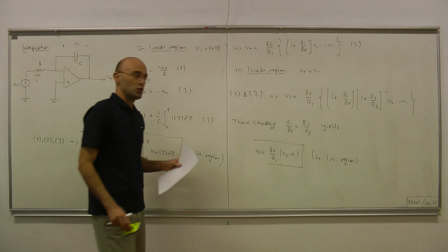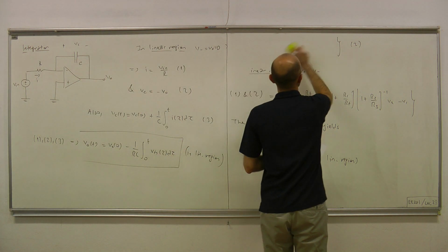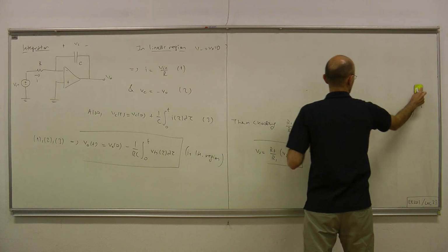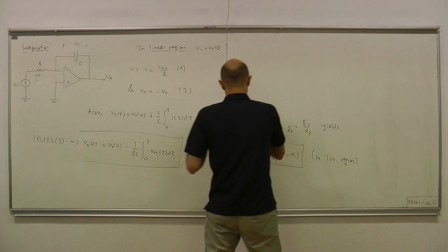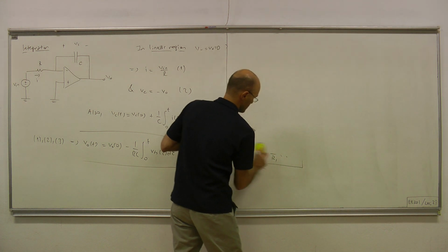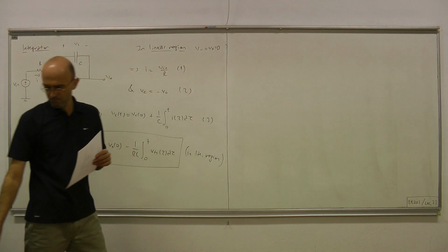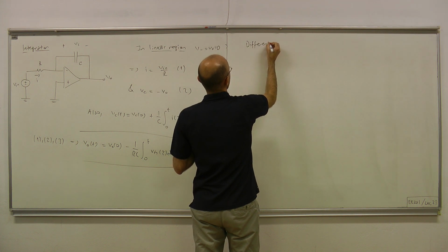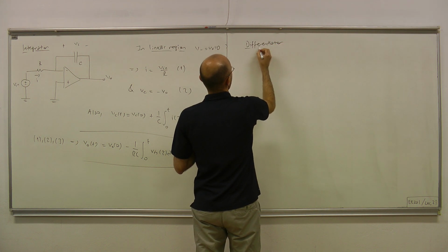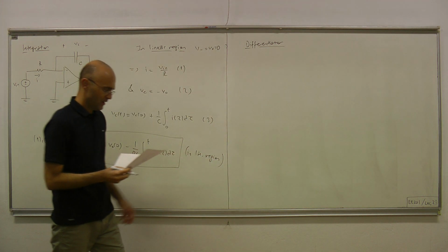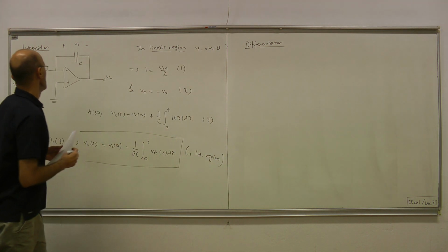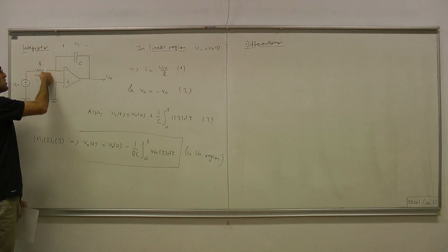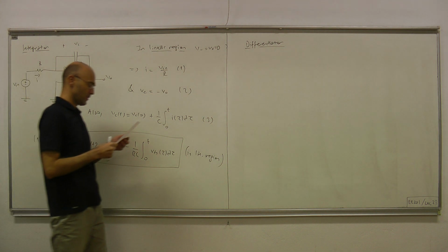This is therefore called an integrator circuit. Let's also talk about the reverse operation, differentiation: a differentiator. It turns out that all we have to do to obtain that derivative operator is replace this resistor and this capacitor.